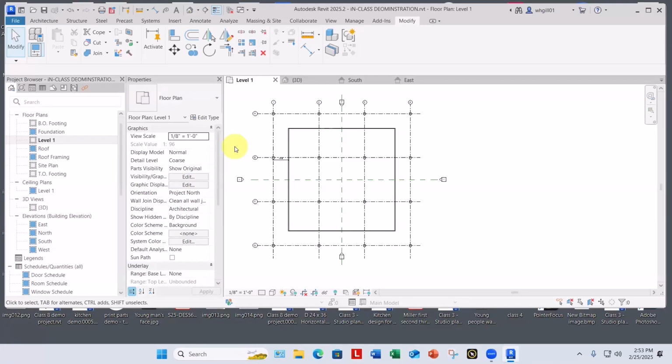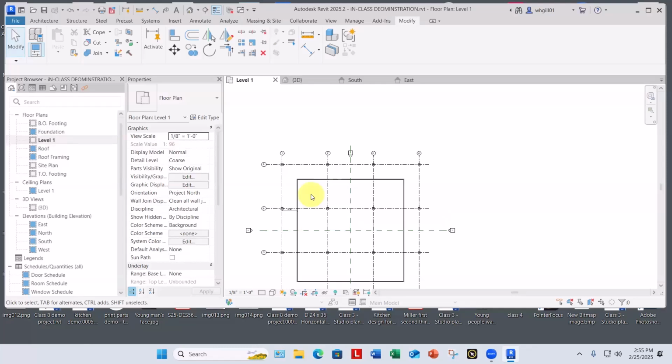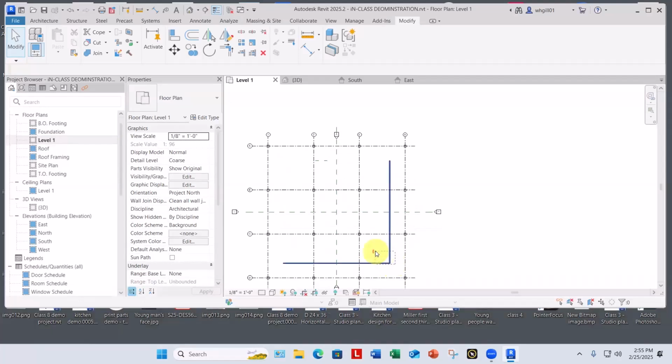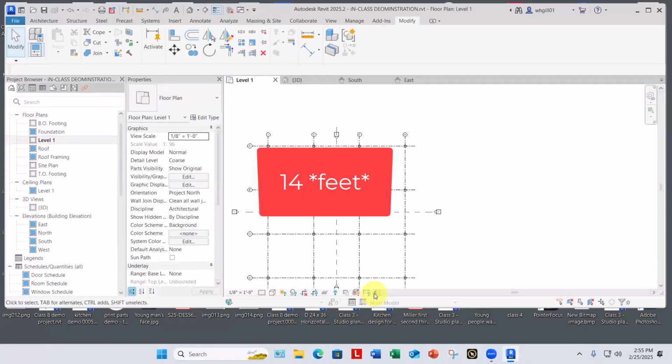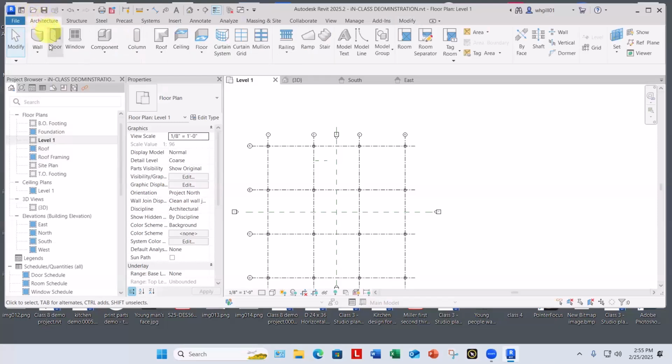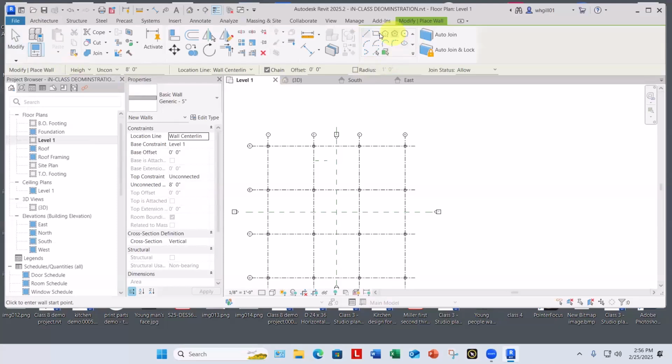Remember, that's set in, and then the building comes out and goes up from there. You want to see an even easier way to do this? Okay, let's get rid of these guys. I know I need a box of a 5-inch wall, and I want it 14 inches in from the outside edges. Think the Revit way, draw it first, and then make it accurate. So let's use the wall tool, architecture, wall. I'm just going to draw a box. I won't even get near those guys.